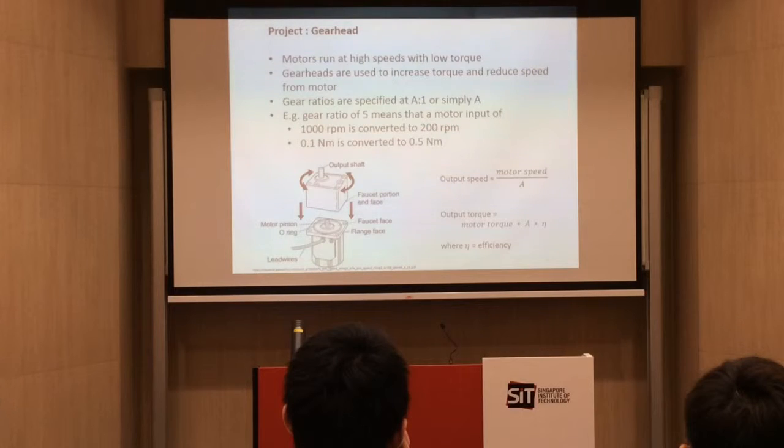But the gearbox is not necessarily efficient, so we also have a term relating to the efficiency of the gearbox. So actually output torque is less than this theoretical number of your torque times gear ratio.